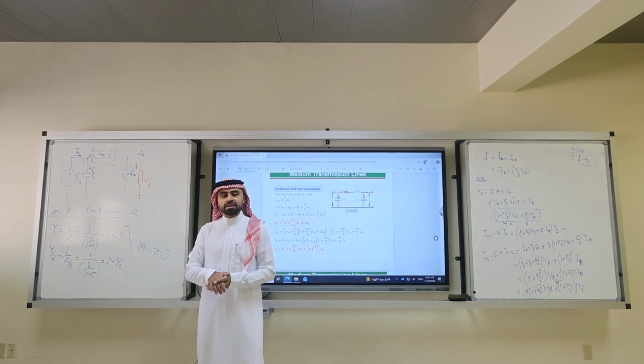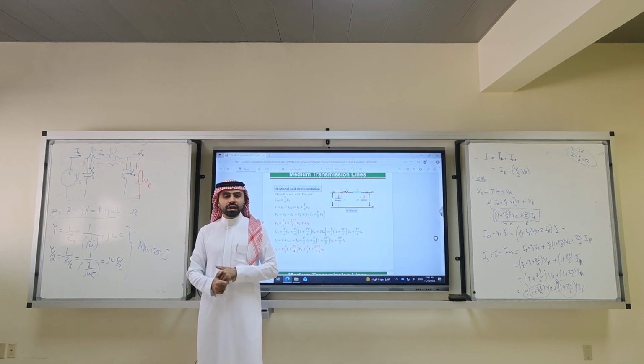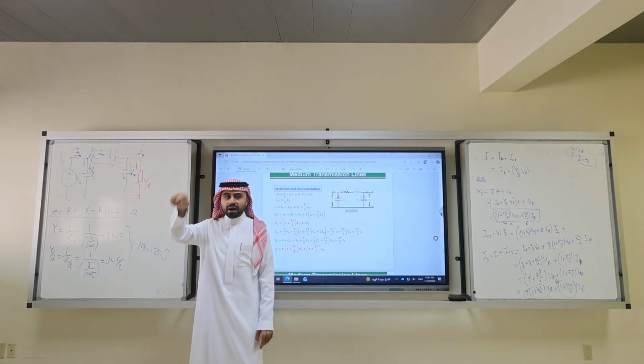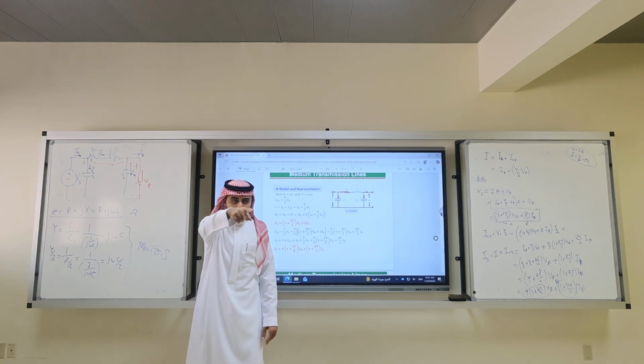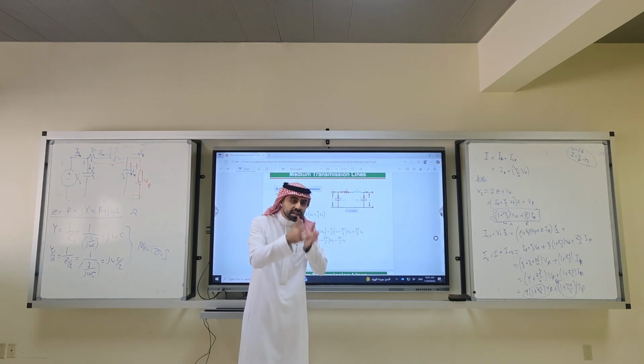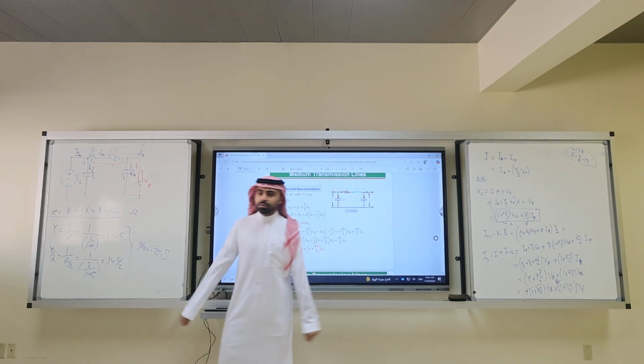In the 80s, 70s, even early 90s, division for big systems was very expensive. Until today, it is better to multiply than divide. You don't believe me? See how your calculator, if you do 1 over 5 plus 5j, takes more time than if you multiply. And you all see how you struggle with dividing by complex numbers. Clear? So why do we use admittance? Because it's easier for software computing. Please keep that in mind, okay?